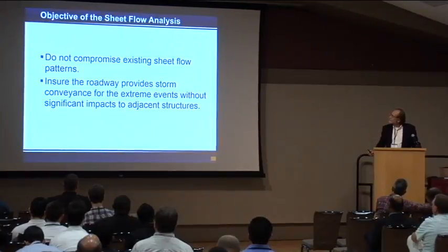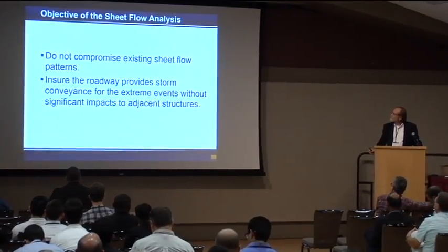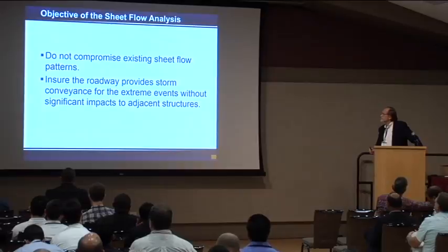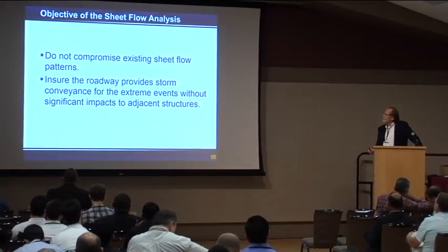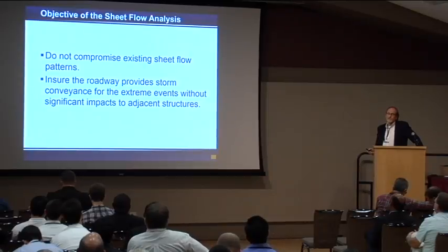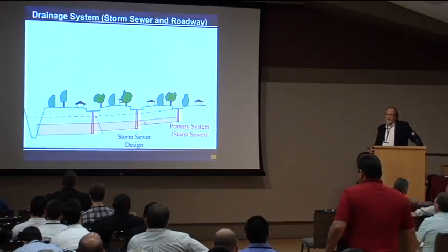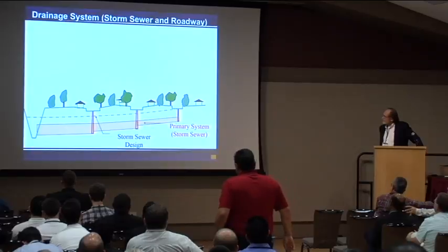projects. The main objective of a sheet flow analysis is not to compromise any existing sheet flow patterns, and to ensure that the roadway provides storm conveyance for extreme events without significant impacts to structures. This is better depicted by this diagram.